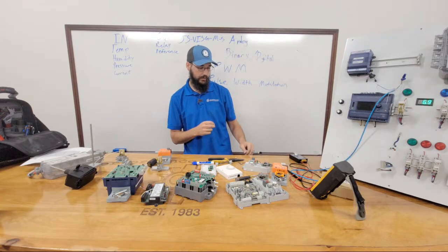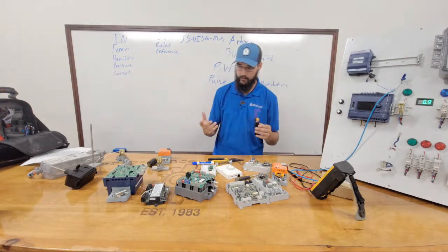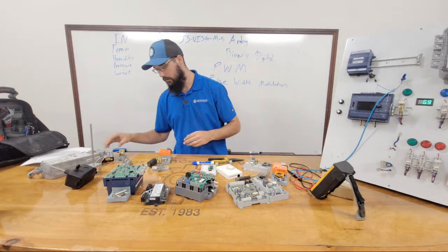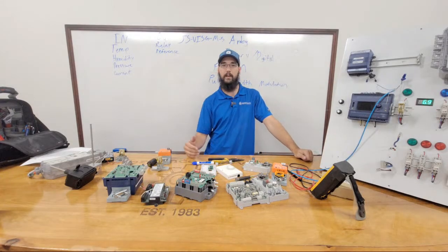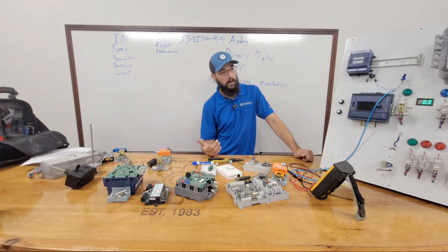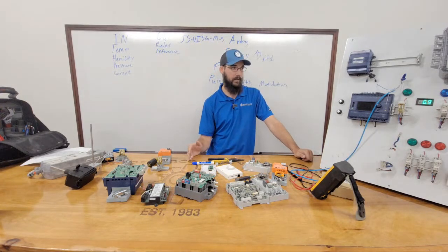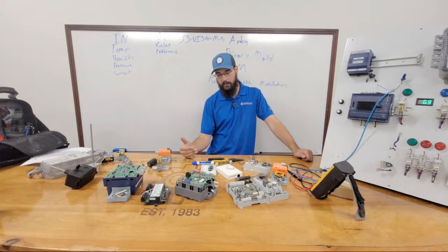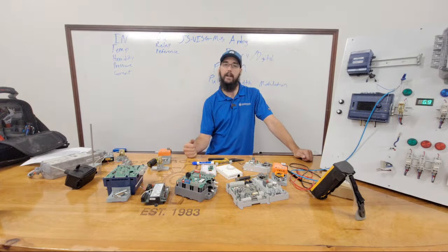So one of the first things you can do when you begin to question, okay, why is this not opening or whatever, right? You go to the front end and it says that this damper is supposed to be at 100% position. You walk up there and it's actually more like 50% position, okay? That would be an immediate opportunity to say, well, we may have a calibration issue.